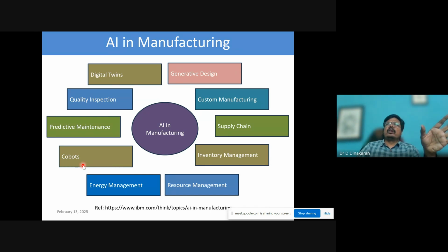Number two, if you have say 15 to 30 different components where the process sequences are different for each and every component. In robotic operation in the Industry 3.0 scenario, the robot will execute constant repetitive programs. But in this scenario, with the help of a vision system, we can decide what component is coming and what sequence of operations needs to be carried out for that component with the machines or other equipment. Accordingly, the robot will change the sequences automatically.